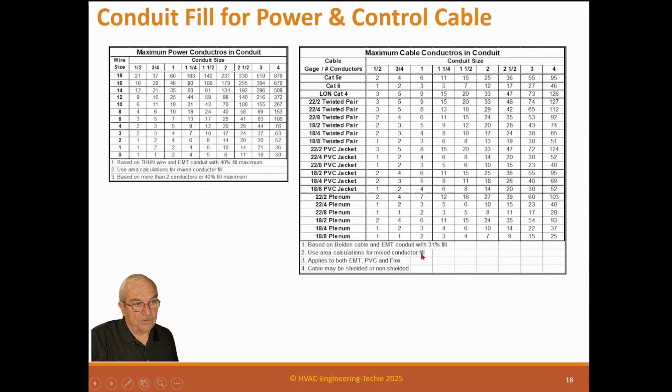Use area calculations for mixed conduit fill. So if you're going to mix a bunch of different cables, which you can do, then you got to use a calculation. This applies to both EMT, PVC, and flex. Cable may be shielded or standard. So if it has shields or is non-shielded, it makes no difference, it's still the number of wires. So this is a pretty handy table to have if you're an installer.